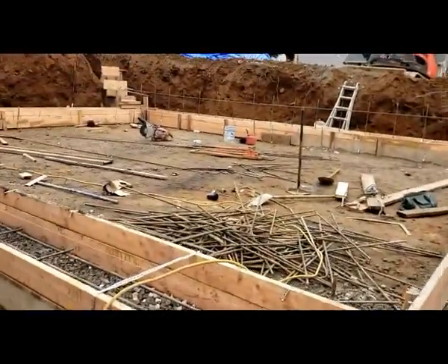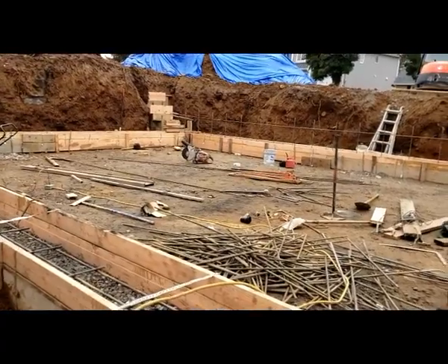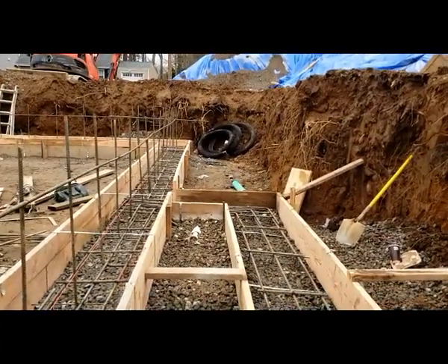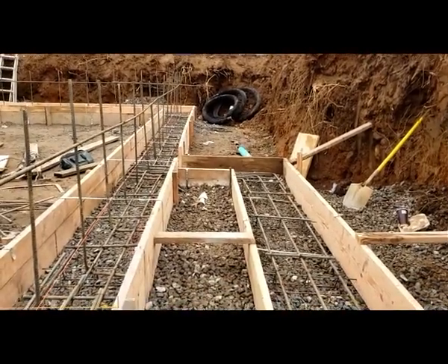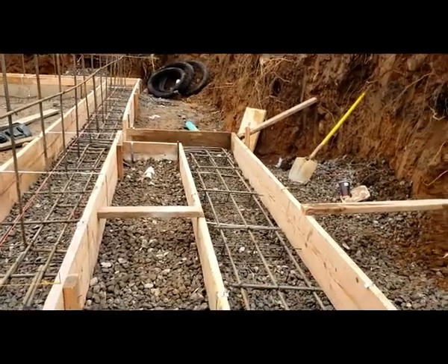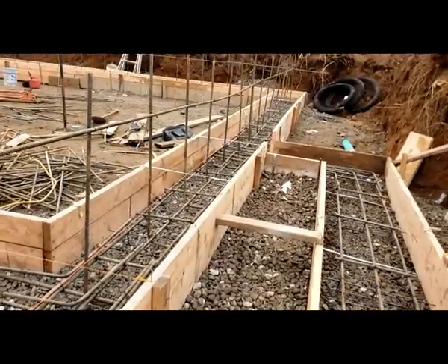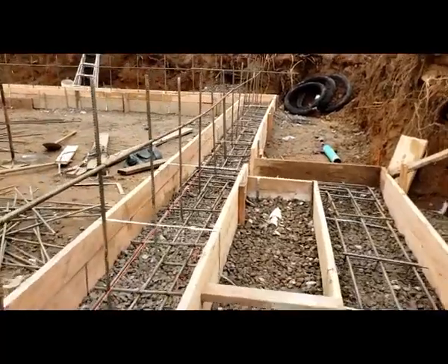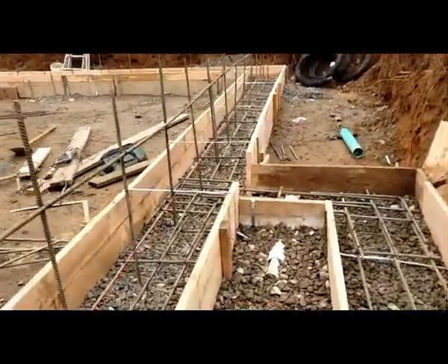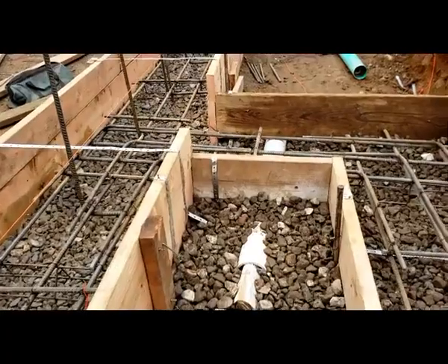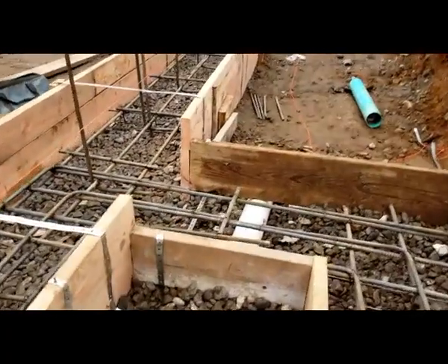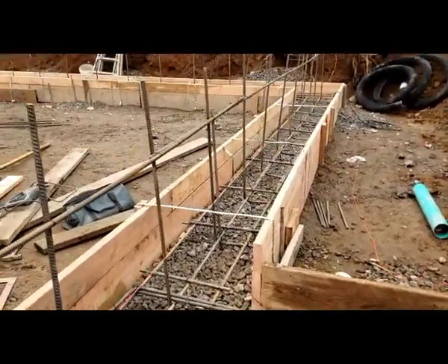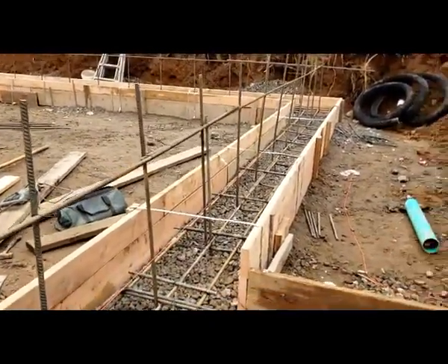On top of the footing, we're gonna pour the concrete slab. Now you need to have the landing for the stairs at minimum 4-inch lower, so when it rains and snows, the water doesn't seep into the basement. And if you see here, you have my pipe here. This is a drain pipe, so we're gonna connect this to a drain pipe before we pour, of course, the slab.